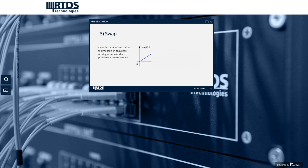The third one is swap. Swapping the order of two packets is to simulate a non-sequential arrival of packets due to problematic network routing. For example, packet A and packet B may have different network paths. When they arrive at the same destination, they may arrive out of order. How is the subscribing IED going to react? That's what we're going to find out.